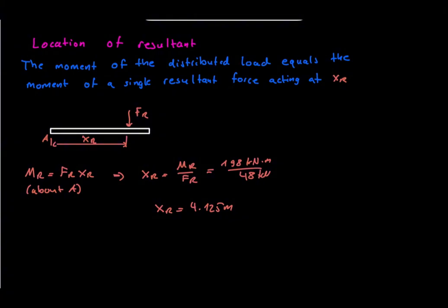For any distributed load function, the resultant force is the integral of W(x), and the location comes from the first moment divided by the resultant force. Geometry formulas are just special cases. Calculus is the general method.